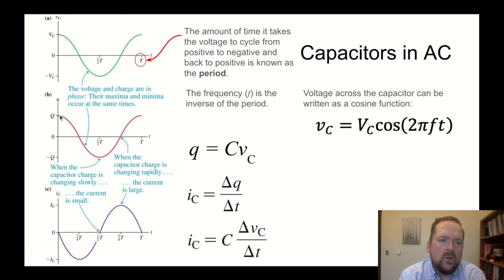But as the charge starts to leak off the capacitor, the slope of that graph gets steeper and steeper and steeper for a while, at least until here. And it's always negative. So there is a negative current that we're getting up until that point. And now the slope is getting less and less and less negative during this part. So that's, I guess, an increase, or a current that's going back towards being a current of zero. Here's another place where there's no charge change, so there's no current.